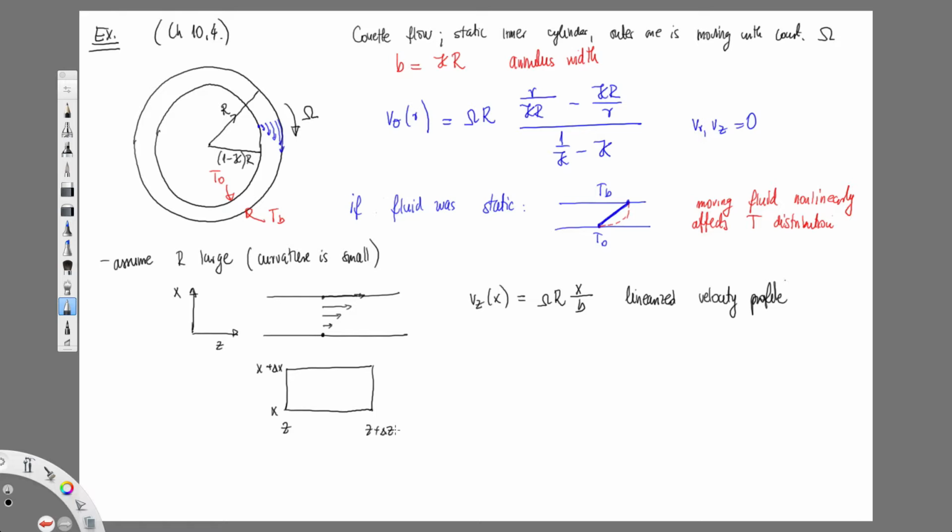And what I'm looking into is this energy flux E. So when I look at my balance, I have stuff quantified by my energy flux vector, which is convection, any work done by molecular forces, and the temperature gradient driving things. And then I have work done by the outside forces, which here we will neglect. And we will assume no reactions, so I don't have any creation of energy within this volume. So basically all I have to look at is the balance of this energy flux.